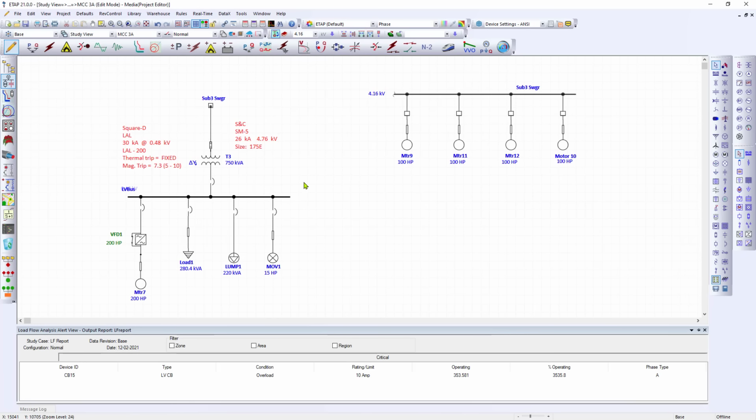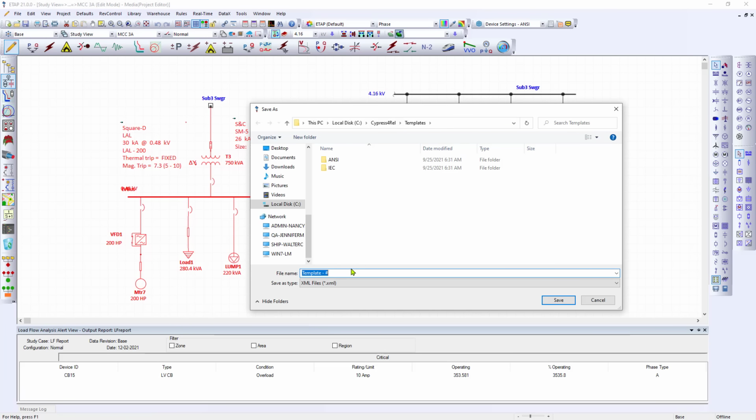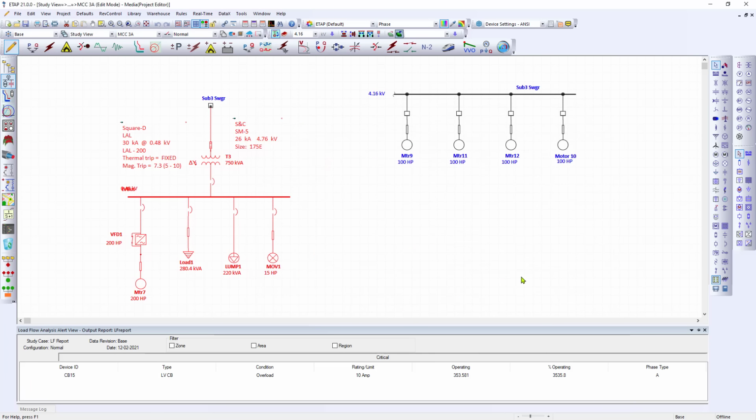As we built this model previously, if I recognize that this model I've used consistently in other projects, I can highlight this, and here on the AutoBuild toolbar we have templates. So I can highlight the portion that I want to save as a template. I click Save as Template. I can identify it and just call it low voltage bus if this is a common application and design for me. I save it in any location that I want, and now I can share this low voltage bus with anyone within our organization, or I can just send the file and use it in any project. I never have to rebuild it.